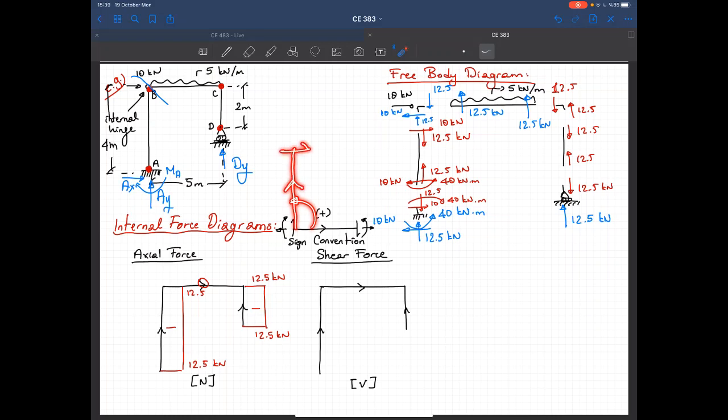And in that case, that's the direction of the positive forces. So at the top I got the same direction of the force. At the bottom they are in the same direction. So here I have a constant shear force, a positive constant shear force, whose magnitude is 10 kilonewtons.